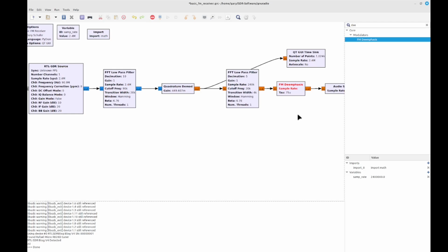Because frequency modulation is complicated, the signal will have more problems due to the higher baseband frequencies than the lower frequencies. So to get around that, to help deal with that, they put in a pre-emphasis circuit which gives more energy to the higher frequencies to make it more robust for dealing with the propagation.